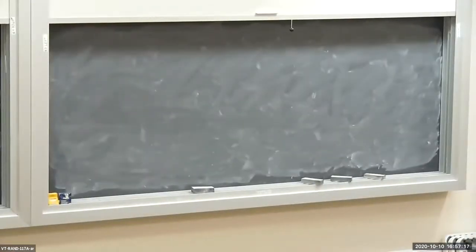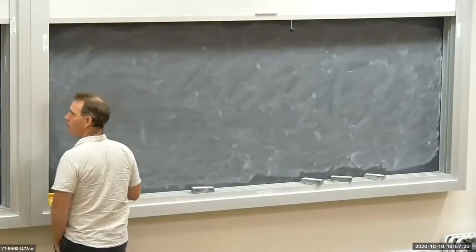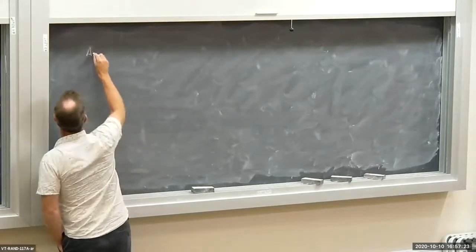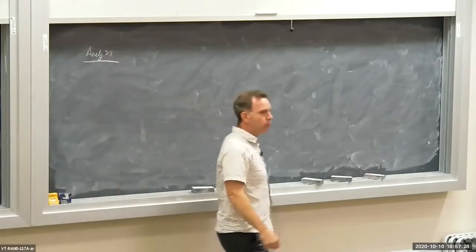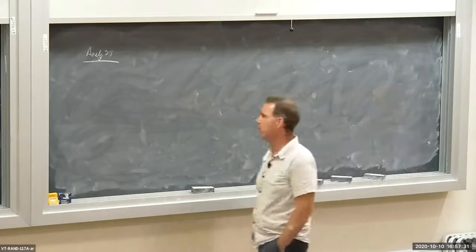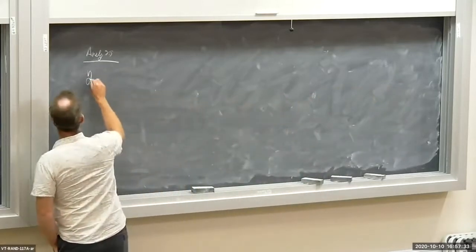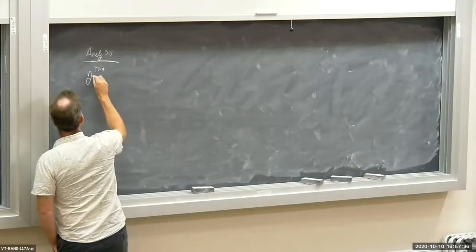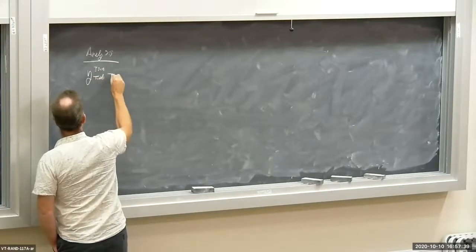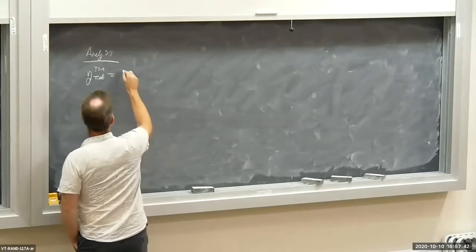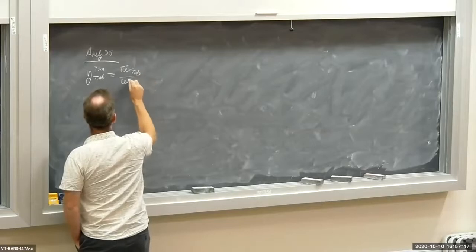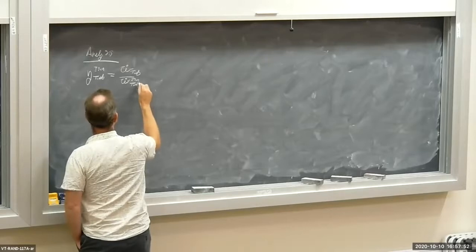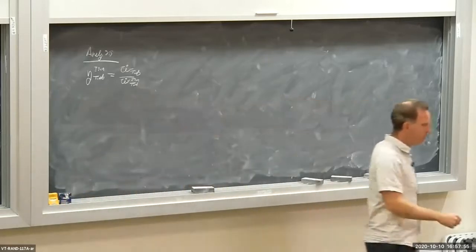Okay, so I want to find the work, or specific work, of the real turbine. So I want to find the real work, or the work for the actual device. If we write down the definition of isentropic efficiency for a turbine, not a compressor, a turbine, we get W dot turbine divided by W dot isentropic, reversible or isentropic turbine.